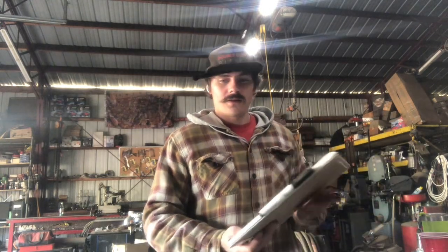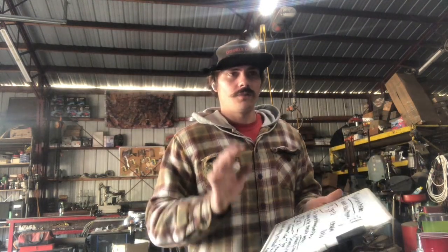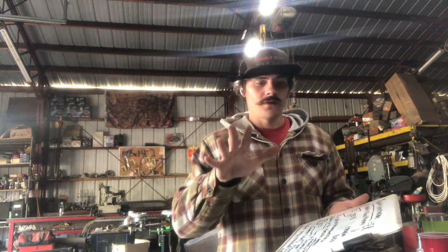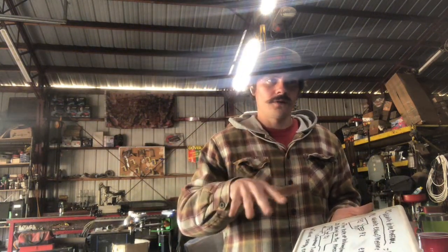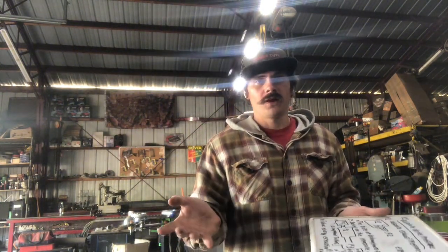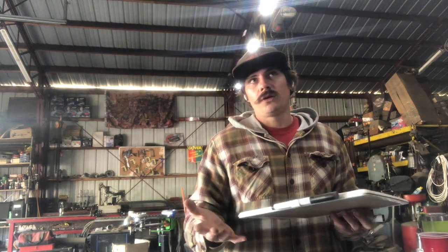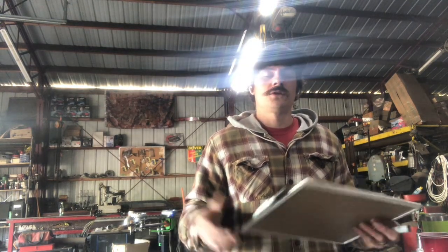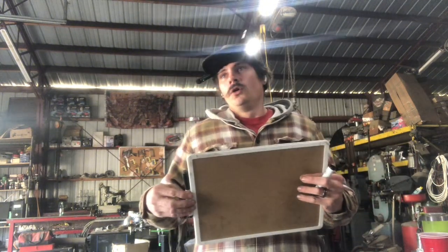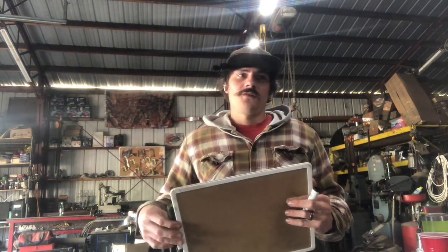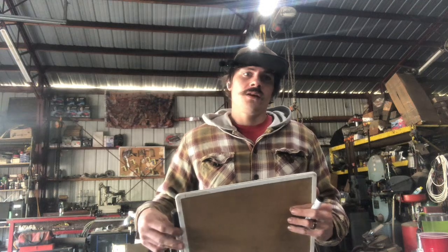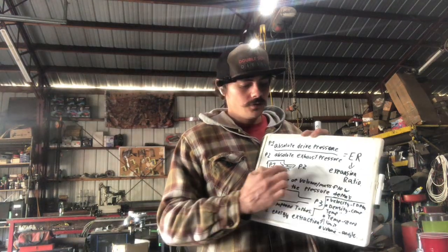At the very end of this, or in the next video, we will plot out some points on a turbine map. If you go look at turbine maps, you'll notice that almost all turbine maps max out at a 3.0 pressure ratio. Or expansion ratio, pressure ratio, it's the same thing for these. That is because the gas velocity can't go any faster, because you're transferring something to atmosphere.